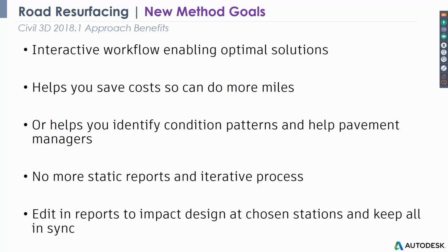In the past, a lot of agencies, because they can't go through this level of detail, used to do, let's do a 2 inch overlay, or 2 inches of leveling and then overlay, or maybe 2 inches of milling as a standard contract, and do that. While you are doing the right things, it is not going to take your dollar value into a sufficient number of miles of rehabilitation projects. So if you save the cost by doing a prudent design, you can actually rehabilitate more miles, which is the key selling point that we see most DOTs focusing on now.